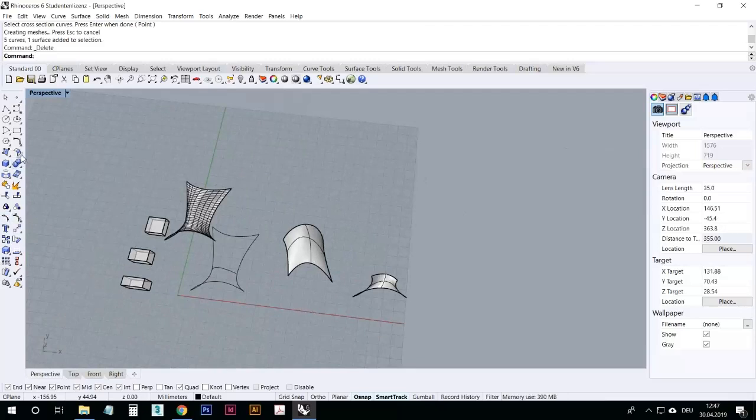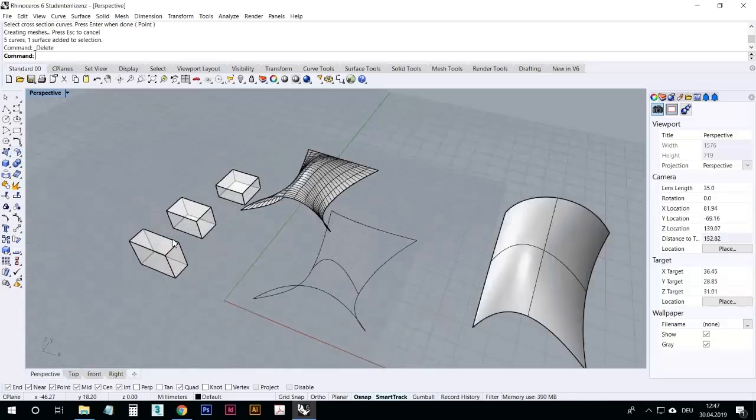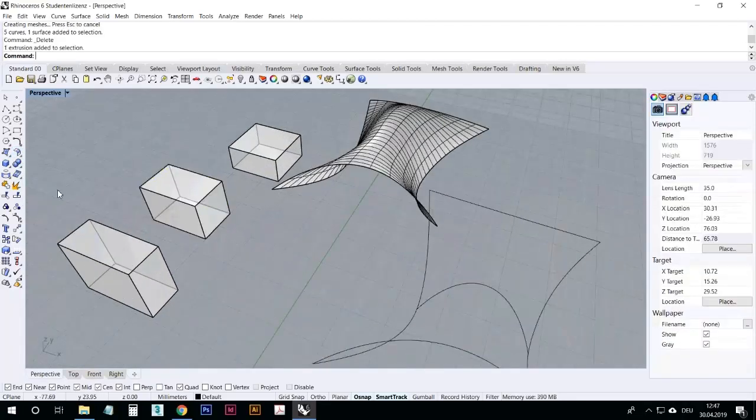We can go further. We can look into surface tools, which means you can fillet your surface, you can blend it. So what does that mean? You get a rounded surface edge. So we have here, for example, our boxes. So if I go there and I click and I say select first surface to fillet, radius 1, I can just say something else, radius 5 or something.